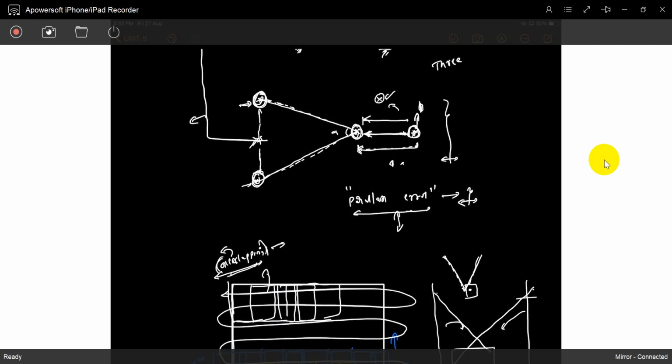It is compulsory that you fix that parallax. That is the parallax error. You have to fix that parallax error, and then only can you get exactly the depth. If you know the depth between those two points, then only can you draw a three-dimensional view of every point.